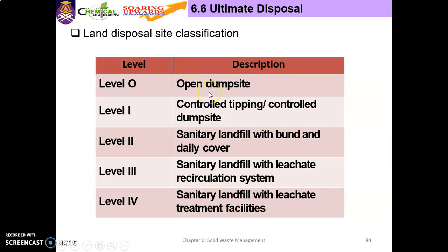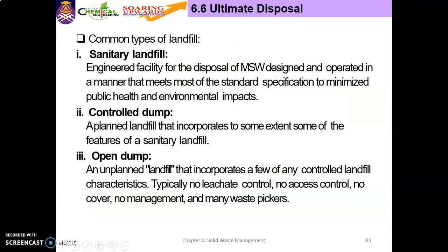Land disposal site classification has certain levels: open dump site, controlled dump site, sanitary landfill with bund and daily cover, then one with leachate recirculation system, and lastly Level 4, sanitary landfill with leachate treatment facilities. The common types of landfill being used up to now: the first one is sanitary landfill, an engineered facility for disposal of MSW, with standard specifications to minimize public health and environmental impacts.